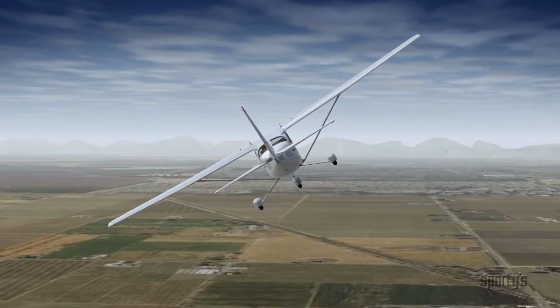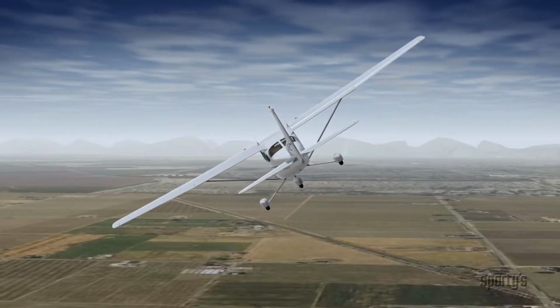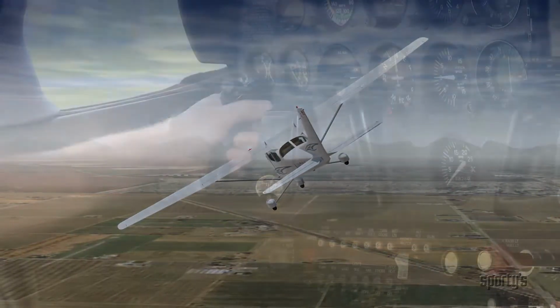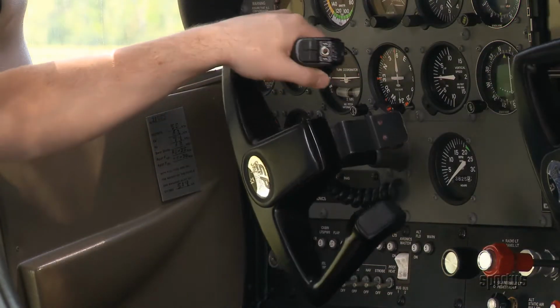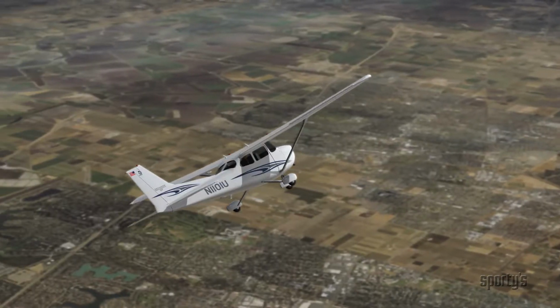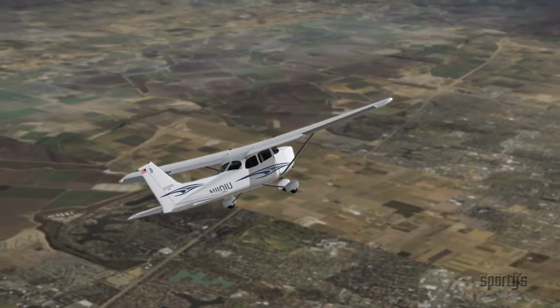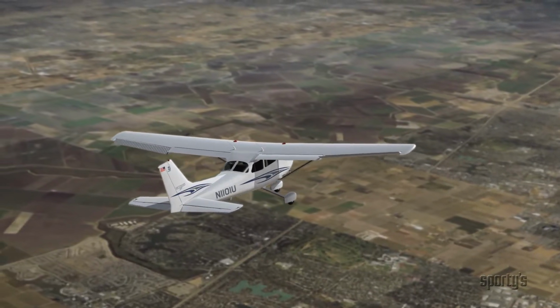When the ailerons are in the neutral position, the aircraft tends to stay in the bank until the yoke is turned opposite the bank to make the ailerons roll the airplane back to a wings level position.